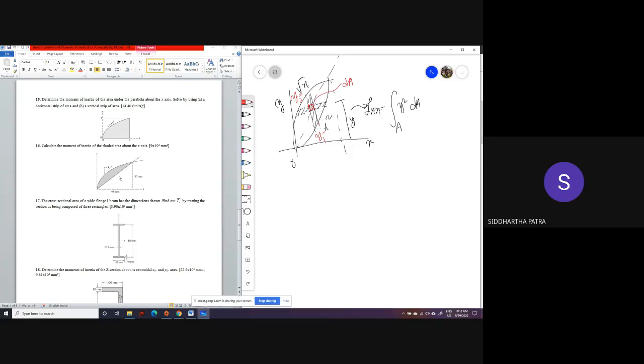But then for rectangles, there is something called the radius of gyration, which is basically this by area. Now imagine there is one area which is very close to the x-axis. Now the same area oriented like this. So this is x. This time it mostly spans away from the x-axis. In the second configuration, it will have more moment of inertia about the x-axis.